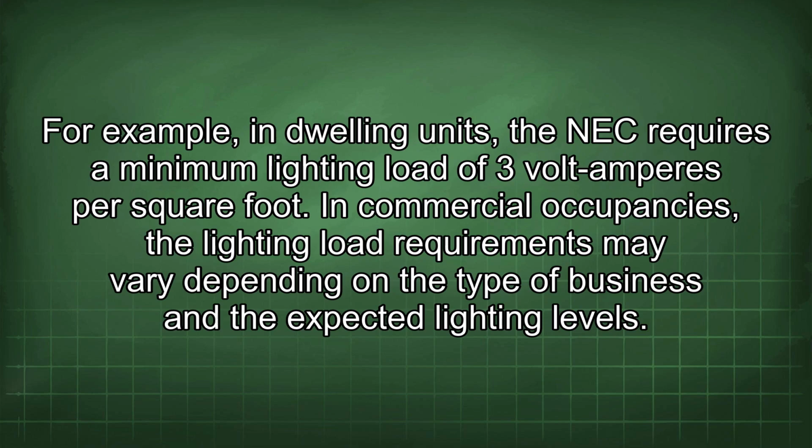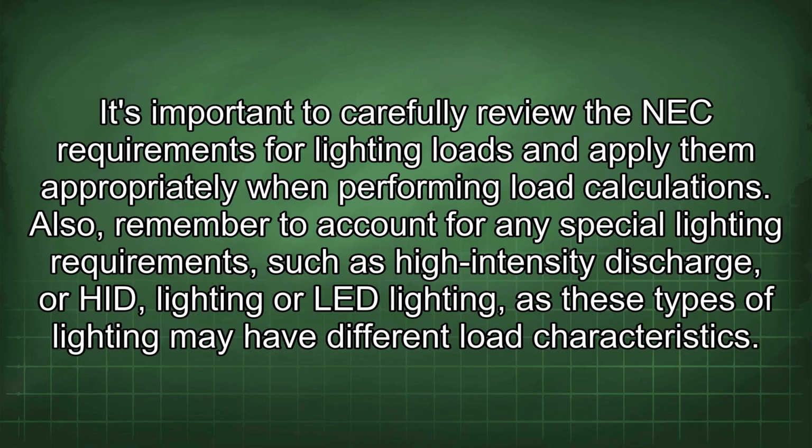For example, in dwelling units, the NEC requires a minimum lighting load of 3 volt-amperes per square foot. In commercial occupancies, the lighting load requirements may vary depending on the type of business and the expected lighting levels. It's important to carefully review the NEC requirements for lighting loads and apply them appropriately when performing load calculations. Also, remember to account for any special lighting requirements such as high-intensity discharge, or HID, lighting or LED lighting, as